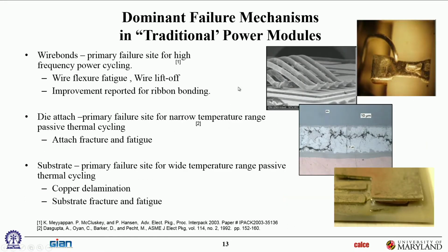So here are some typical interconnections. And the failure mechanisms, like I said, there's nothing intrinsically different about them. You get wire bond failures here. These are typically not, well, some of these are potted, molded over, but many times they're not in power electronics. These are usually much thicker wire bonds, not the thin kind of wire bonds that we use in microelectronics. Sometimes the interconnections are very, very thick. And then you get failures of die attaches, you get failures of the substrates.